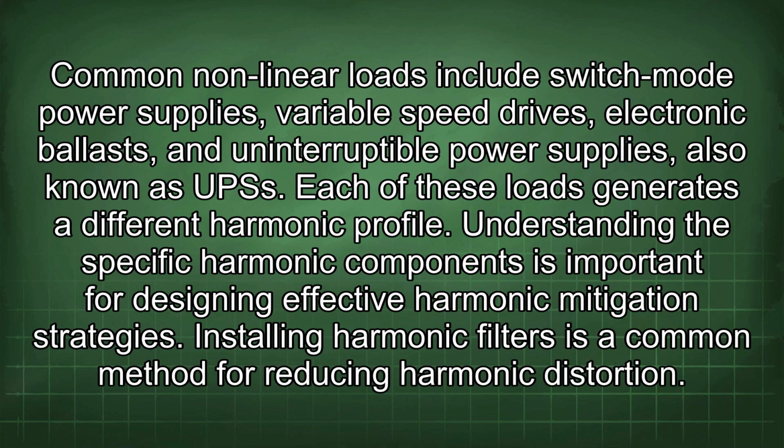Common nonlinear loads include switch-mode power supplies, variable speed drives, electronic ballasts, and uninterruptible power supplies, also known as UPS. Each of these loads generates a different harmonic profile. Understanding the specific harmonic components is important for designing effective harmonic mitigation strategies.